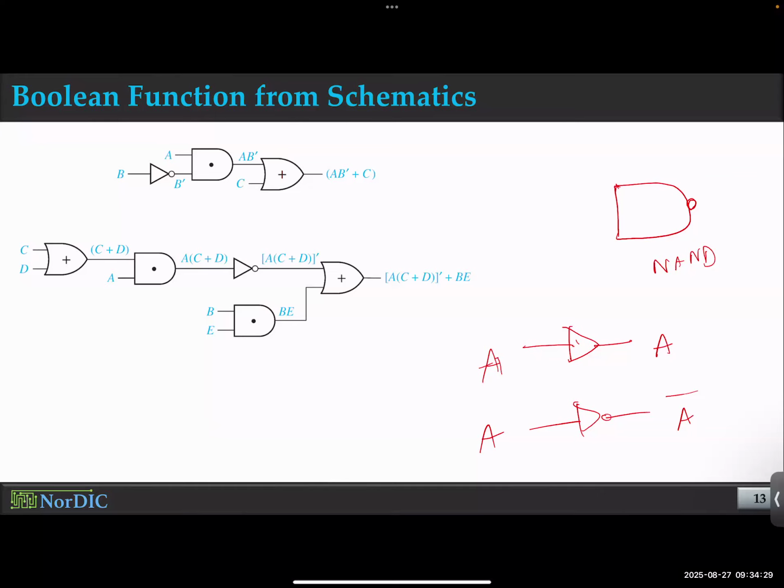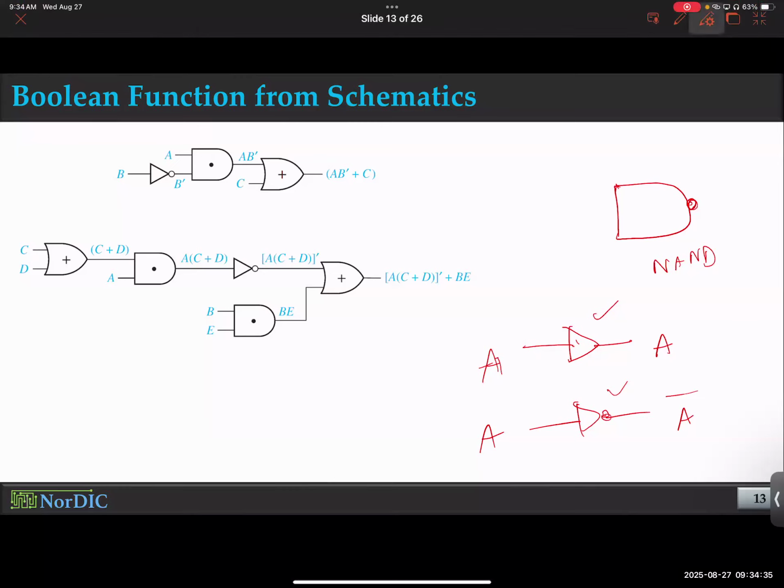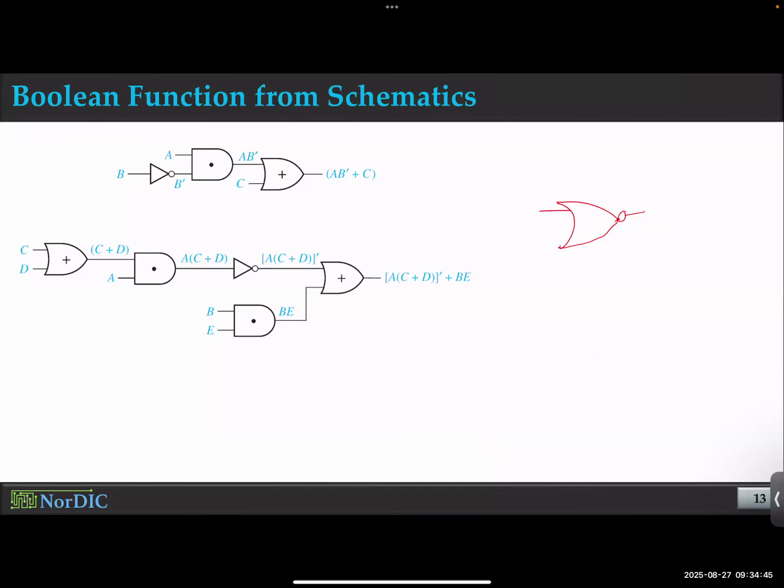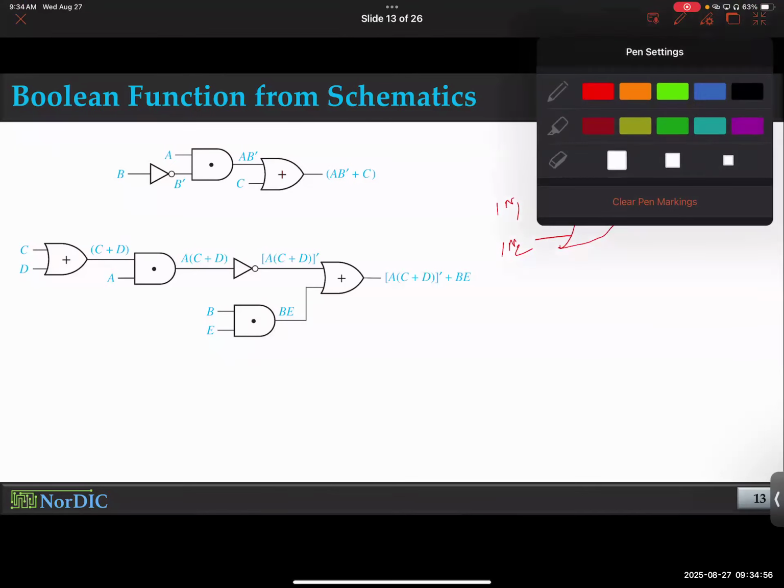Anyways, so see the difference? Whenever you need to have inversion, you add a circle. So this is an OR gate symbol. And when you connect a circle with it, that becomes a NOR gate symbol. Okay. And depending on how many inputs you're dealing with, you can have 2 inputs like this, input 1, input 2, or more, or input 3, right? That's the pretty standard concept.